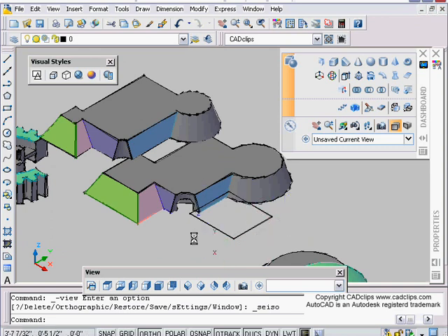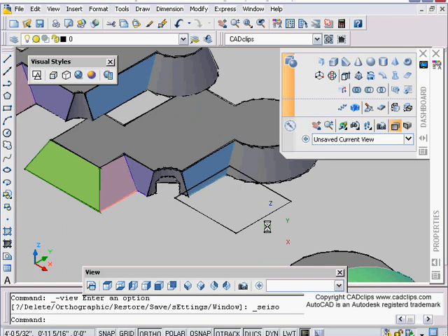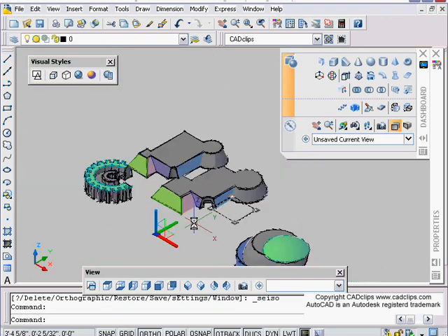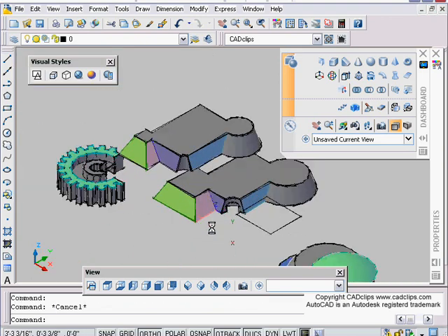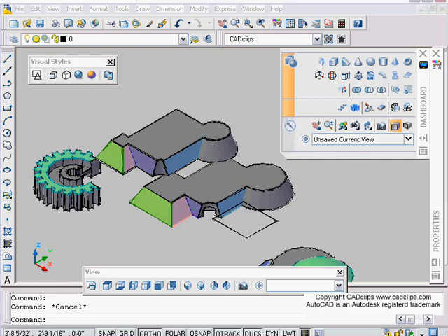The main thing is draw the object on one plane, switch to a perpendicular view, and move that plane up and down. And when you do the slice, I recommend resetting your UCS to the plane that the slicing plane was drawn on. So a couple of little extra tips there. And once again, prerequisite, have a look at our previous 3D videos for AutoCAD 2006.